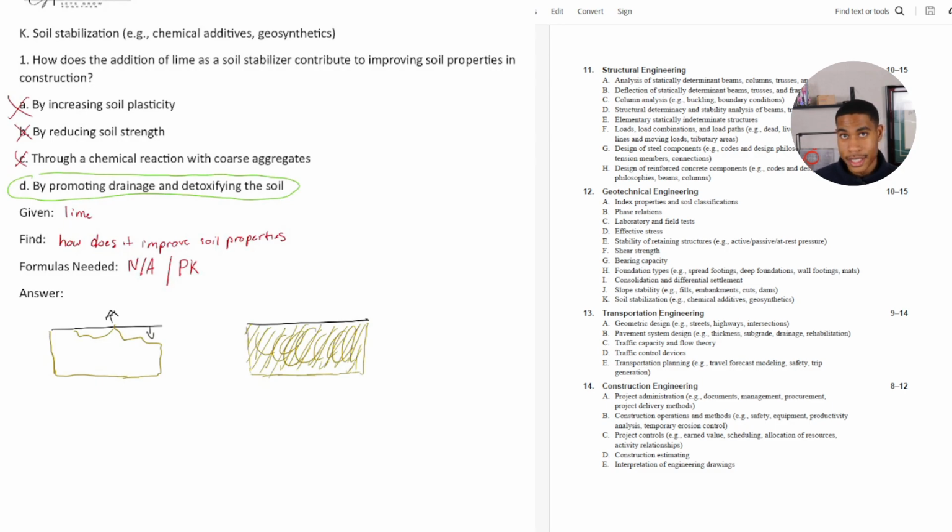so that you can measure how liquidy it is on your next test. Well, in order to do that, to keep your slump cone clean, sometimes what we would do is we would spray our slump cones with lime, and it was like an oil almost, where it would make whatever was on our slump cone disassociate from the concrete, separating the two, so that we could scrub it off and get rid of the excess concrete. So lime is very powerful stuff.